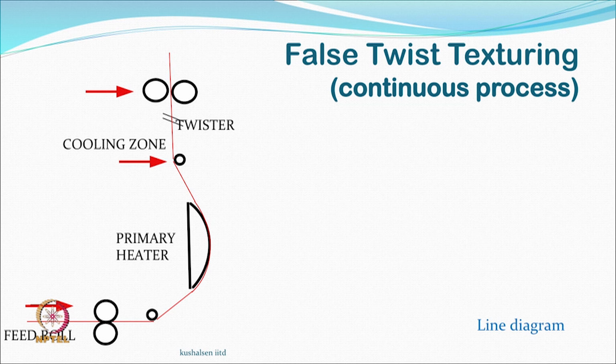So, there is a heater if we are again looking at a thermoplastic yarn. If there is no thermoplastic yarn, then heater is not going to be the one which is the functional part, we will have to do something else. But let us say we have a thermoplastic multifilament yarn, then in that case we have a feed roller and a take up roller, and in between you have a heater.